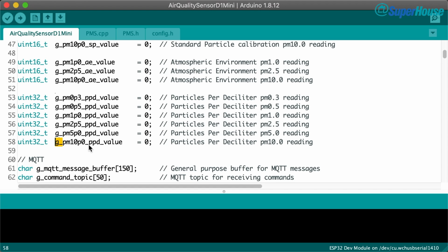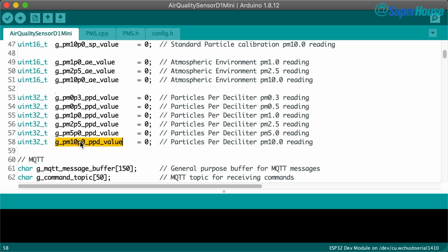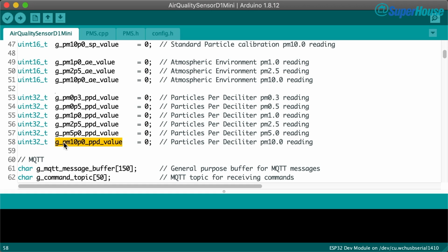This is something that comes out of the Barr Group Embedded C coding guide, and you can see it's got G underscore to signify that this is a global variable. That can be really handy when you're down deep in a program and you are assigning a value to a variable. You're not sure if it was declared within the scope of the current function or if it was something global. Problems caused by wrong variable scope can be really tricky. It's the sort of thing that can have you scratching your head for a very long time. So using this very limited form of Hungarian notation, where we just show global variable scope, can be really useful. I actually resisted the idea of using this G underscore notation when I first started following the Barr Group guidelines, but now that I've been doing it for a while, I've got used to it, it doesn't look jarring anymore, and it's actually really useful.